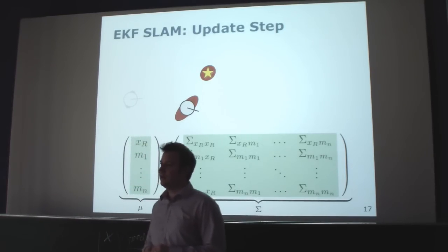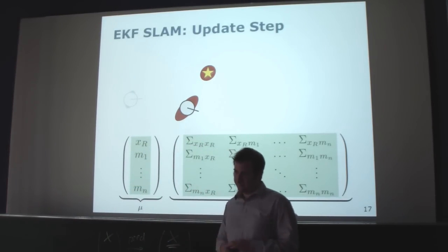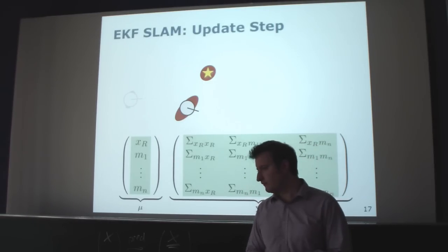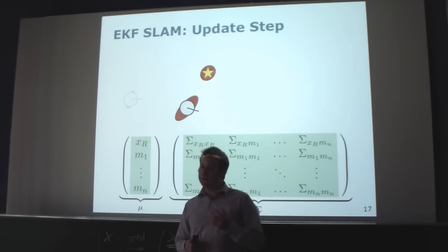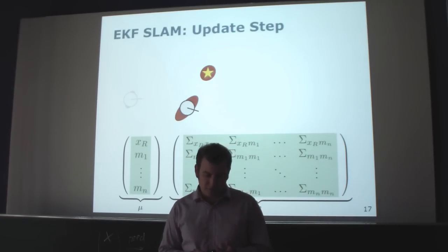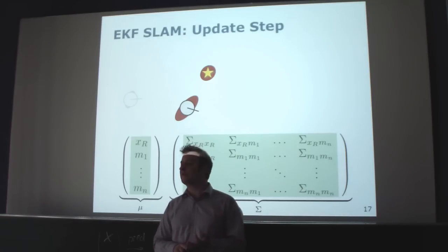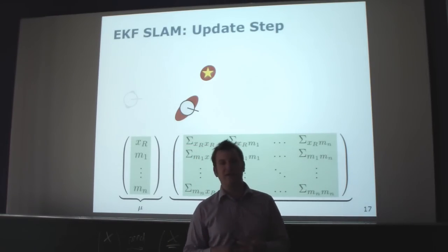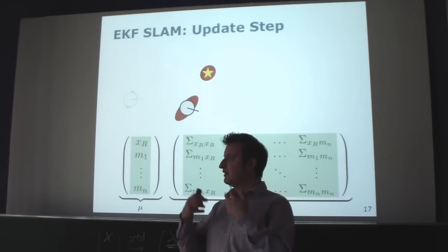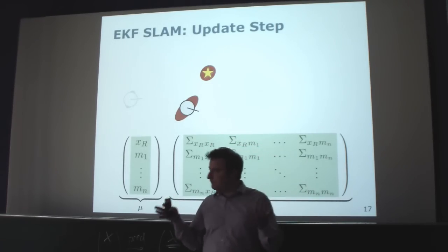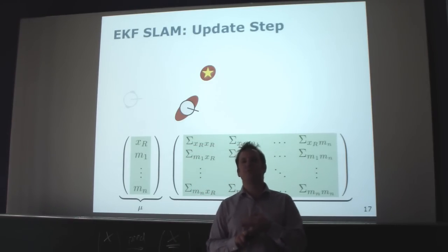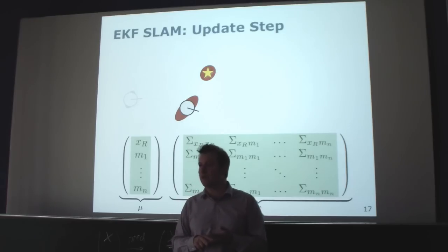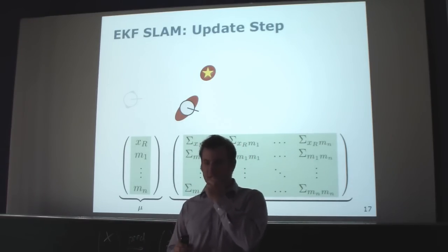And the question is about the previous step. How do we do this data association if we have only the position of the landmark and no labels which can do that? So there are different ways to do that. One thing is, perhaps we are in the lucky situation that our sensor provides some hints. So we have a vision sensor, there are ways for identifying the appearance of objects, my landmarks. So there are different kinds of visual features I can use, which are not perfectly distinct, but which give me a pretty good estimate if two things are the same or not.